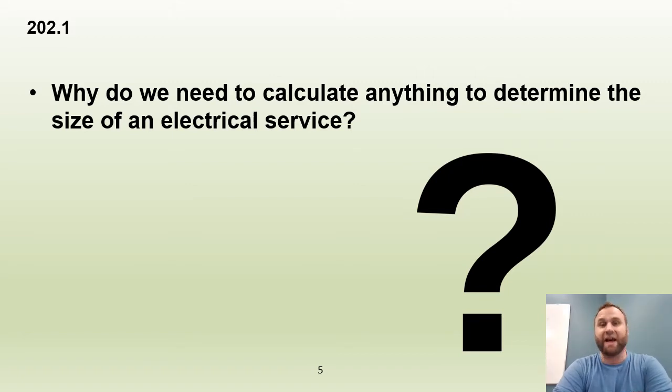No, it doesn't say that. It's up to us as the electrician to figure out what the rating of that house would be if it had one. So in order to figure that out, we need to calculate or add up the total wattage or the total volt amps used in that structure to determine just exactly what that house is rated for and what size of service or overcurrent protection device we're to protect that house with.